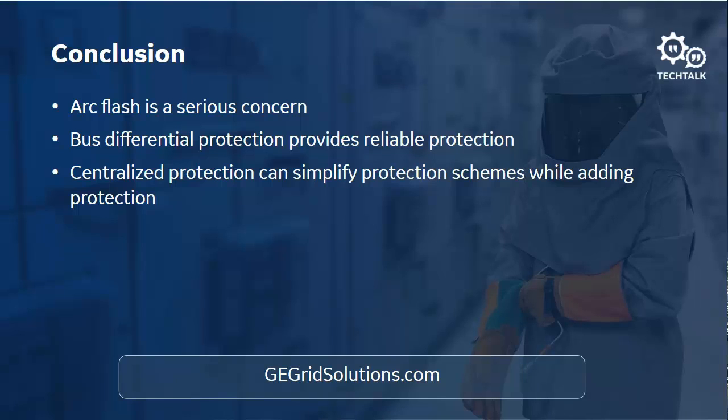And there are other drawbacks to it too, where you can't do reconfigurable buses. It's kind of a stiff solution. It doesn't allow a lot of flexibility. The low impedance gives you a lot more flexibility and a lot more options because now you have access to the individual feeder currents. With the high Z method, you just have one summation current that's available for any type of information post-fault. The low impedance does give you a lot more information if there is a fault there.